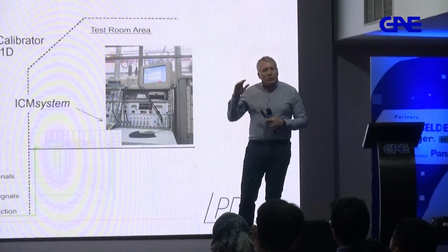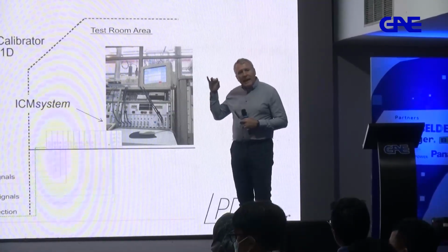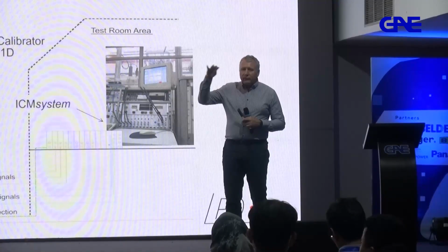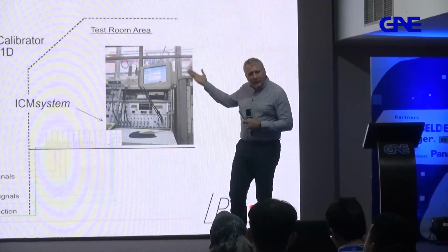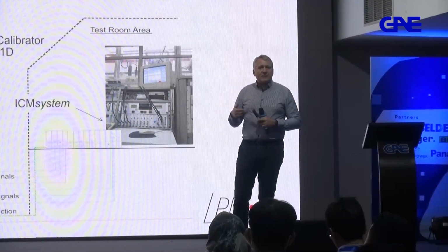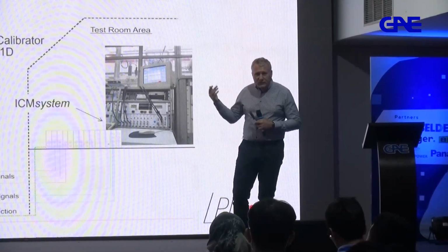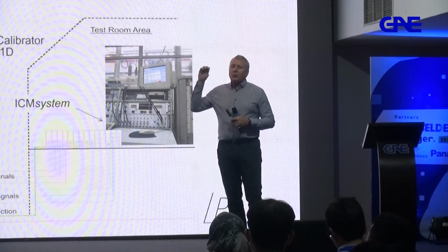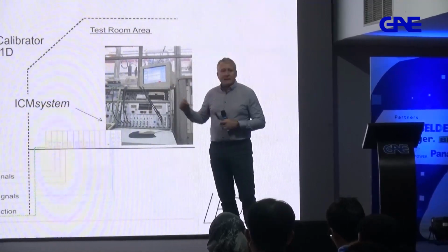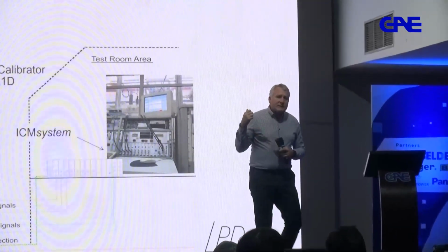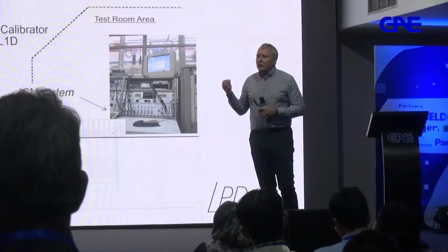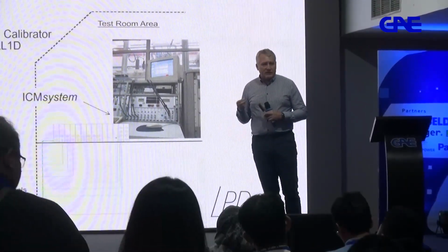When, for instance, you would like to know how this transformer behaves from the high voltage side, you're going to apply a high voltage to all phases simultaneously. So we have test containers that can do that, but the factories do have that implemented, and they will either induce or apply. And during that time, they will test for partial discharge. What does that tell anybody? It will tell you about the quality of that particular transformer.